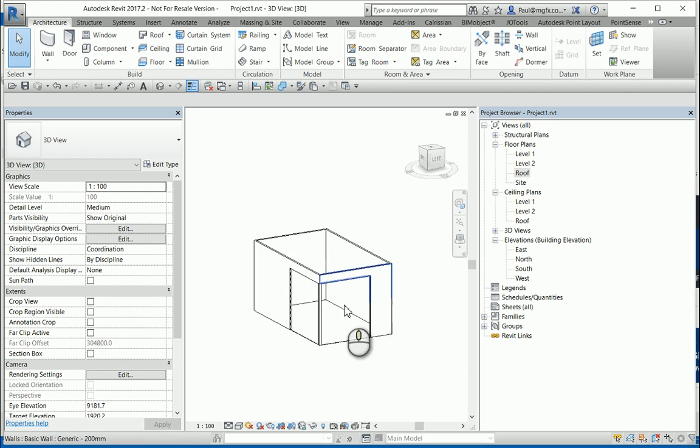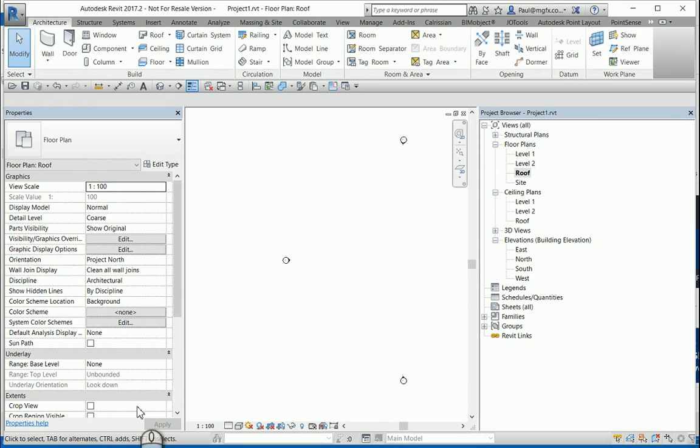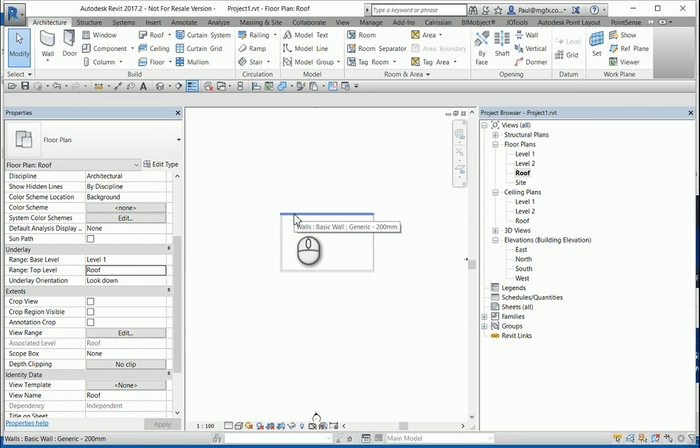What can be seen here is a two-story building, and there is the roof level. We can switch on an underlay which will allow us to create geometry close to where we want. So typically what would happen is one would extrude the roof from left to right or from bottom to top. But let's suppose you wanted to create an interesting roof across the diagonal.